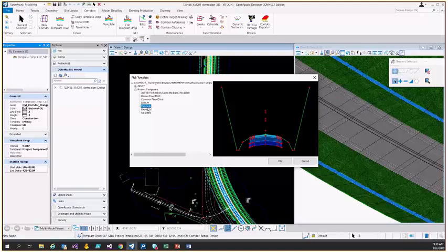So this example one is just my regular end conditions, not a fixed ditch or anything. And then example 1 is my fixed ditch one. One thing you do want to keep in mind is that you'll want your fore slopes and your back slopes to be the same between the two, because obviously if you have a different slope when you make your profile, you're going to have different conditions there. So you do want to keep those the same.